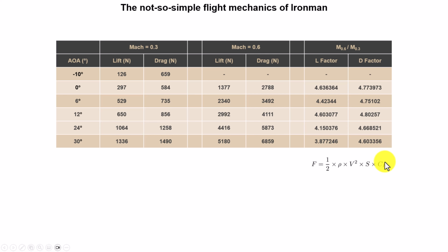And I know that when it comes to lift and drag and compressibility effects, there is a very strong non-linearity here. So if I keep increasing my Mach number, and I already have some results, Mach 0.75, this coefficient will go down a lot, and all the forces will go down. So it's a really bad condition. But let's just sit here, but for those curious, now you can go 0.775. If you want, you can go supersonic, but let's first solve the problem of how to balance everything, because that is our goal. We want to keep about 0 degrees and balance, generate somehow the forces. So this is already telling us we need to use vector thrust like in the first video.